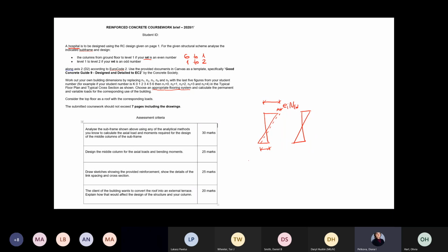And when we calculate our C value, you remember that we have 1.7 minus Rm. So for the calculation of this Rm, we're technically looking at the ratio of the two moments. So one is overestimated, the other is underestimated. So we're technically saying, okay, we have eccentricity, this could add to the greater of the two moments, and by that logic it will reduce the other one, because this moment, E times N, your eccentricity times the axial load, will give you, let's say, tension on the left-hand side of the column or on the right-hand side of the column. So it's a constant moment from top to bottom.